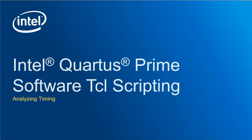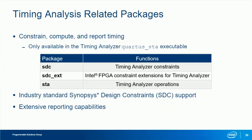We've looked at how to parse through and extract information from compilation reports. Now, let's look at how to create time reports and gather detailed timing information for specific paths using Tcl and the Timing Analyzer command line executable. The timing-related Tcl packages provide a way to constrain and perform detailed timing analysis on your design. All of these packages are available only within Timing Analyzer Quartus_STA executable.